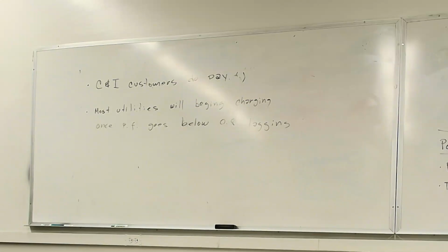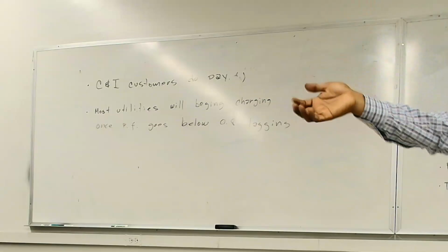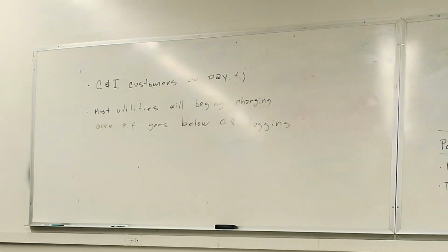So we'll talk about that. How do we size them, and how do we determine the size of the capacitor based on improving it? And the answer to your question is right, because a lot of the commercial and industrial have very heavy inductive loads, lots of induction machines. So therefore, they're consuming a lot. Their power factor is very poor, for the most part.